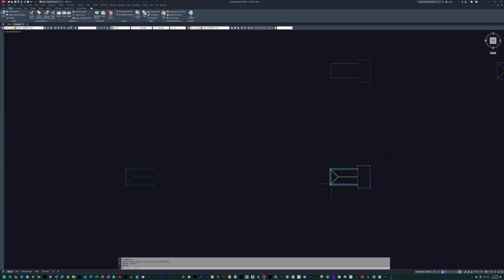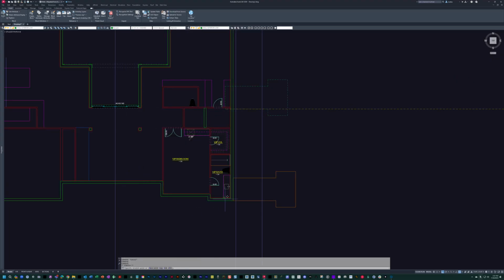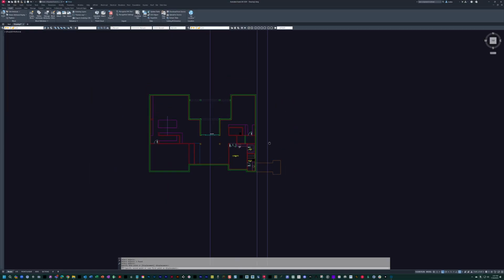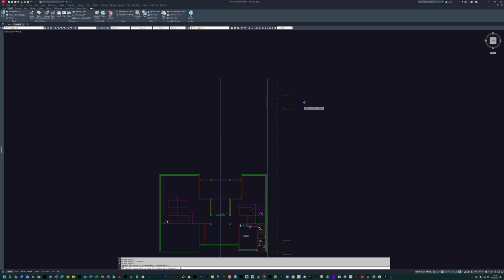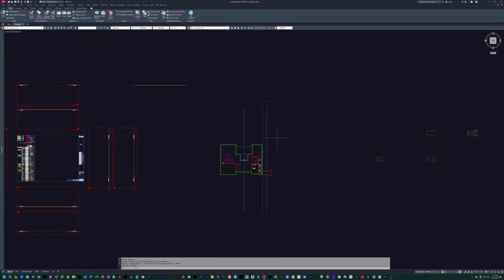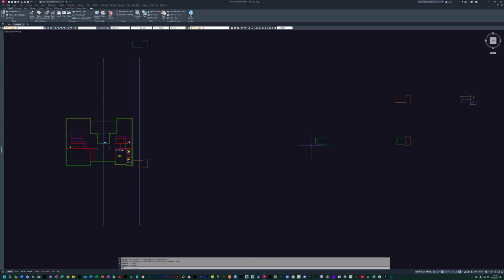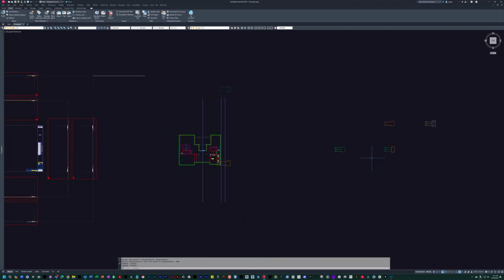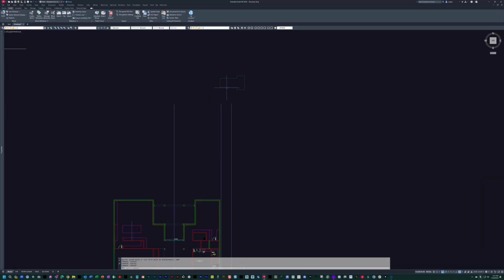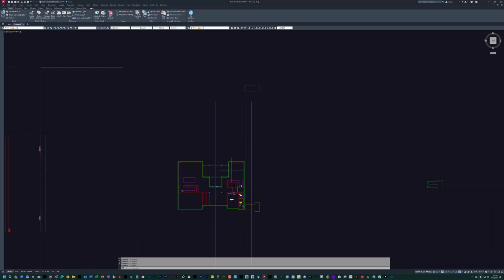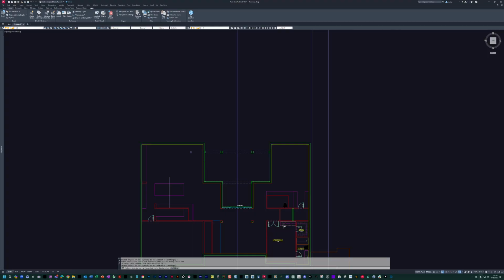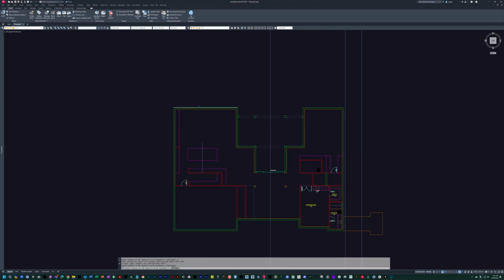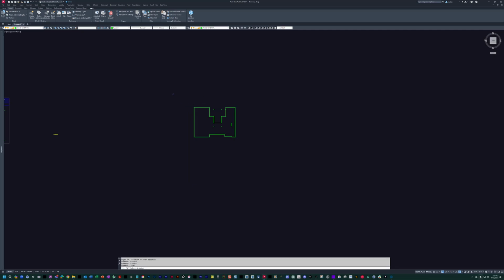This is the exact same block, but it is already changed to a different layer coloring. So I'm going to move this just 150 feet up. Before I jump into the rest of these, you're going to see that by me manipulating one, I can actually manipulate both. So I need the outline of the house. So I'm going to layer isolate my exterior walls. I'm just moving this over because I need a copy of it.